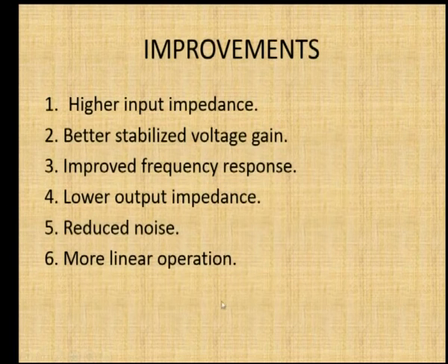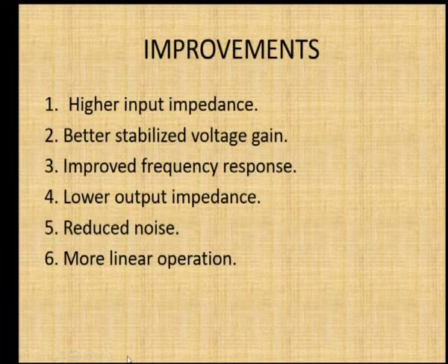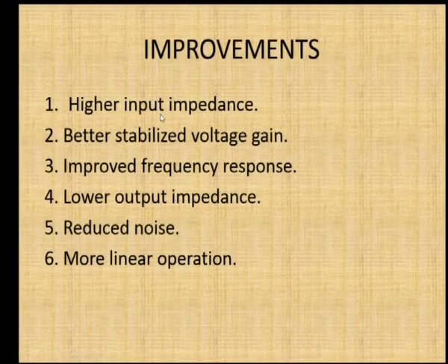We see that if the feedback signal is connected negatively, it is a feedback amplifier. With this negative feedback, the circuit improvements we are going to see are: if you give a negative feedback, you will get higher input impedance, lower output admittance, lower output impedance, stabilized voltage gain, improved frequency response, reduced noise and linear operation.